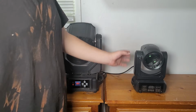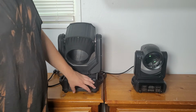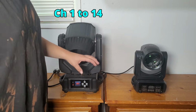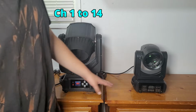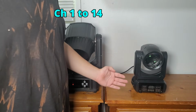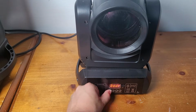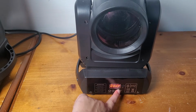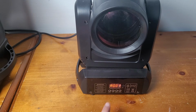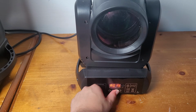Now this moving head, this is the second one in the chain, and since the first one takes 14 channels, it's going to take all of the data between channels 1 and 14, meaning I'll want to start this one on the next open channel. That next channel is 15, since 15 isn't being used. So I'll go on here, hit menu, it's in the address, so let's hit enter to edit the address, and you can see it's set for 1. So I'll hit up until it reaches 15. And let's see, and there we go.